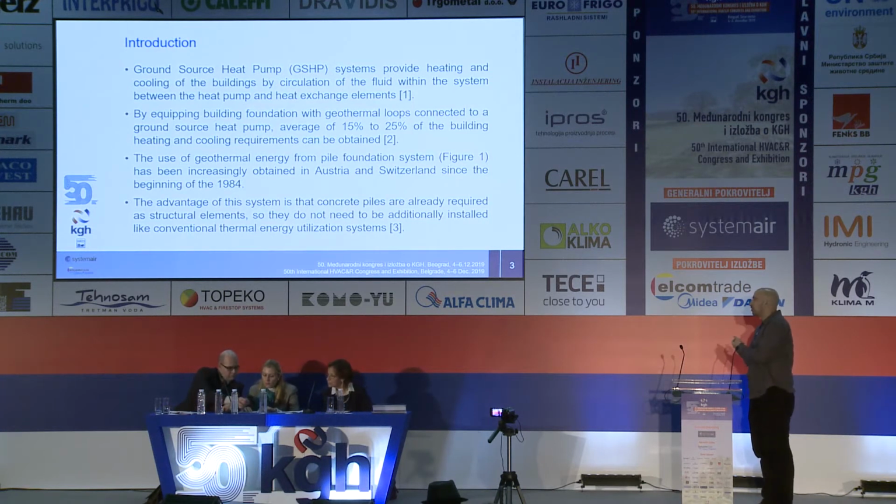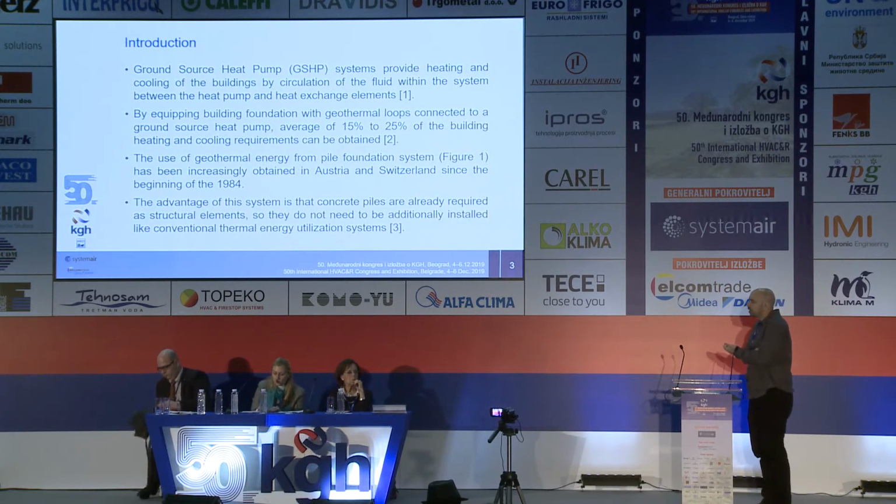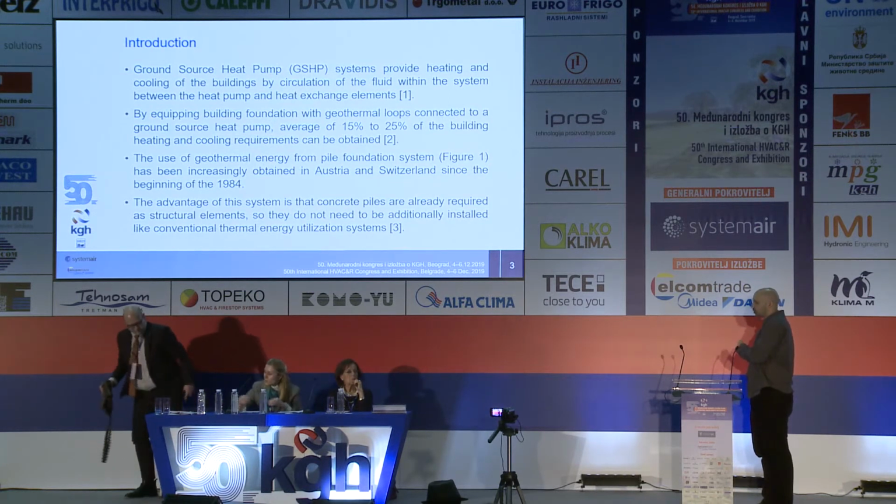The use of geothermal energy from pile foundations began in 1984 in Austria and Switzerland. Basically, the advantage of this system is that we use already required concrete piles as structural elements, so they do not need to be additionally installed like conventional thermal energy utilization systems.